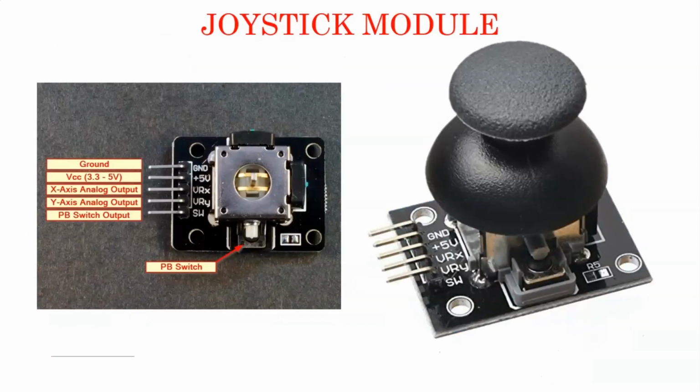This is the joystick module. Its working is simple. It has 2 potentiometers attached to it, whose output can be measured by connecting VRX and VRY to analog pins in Arduino. And it also has a switch which can be connected to a digital pin in Arduino.